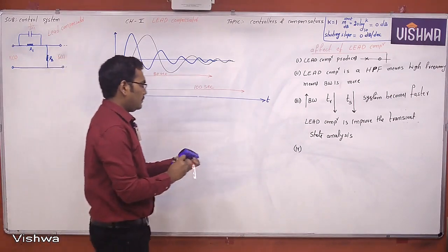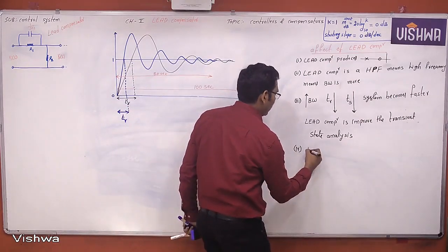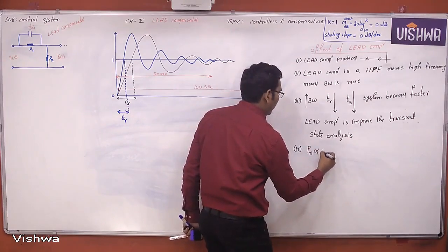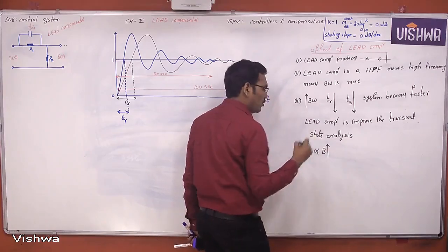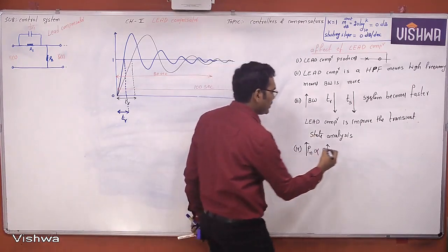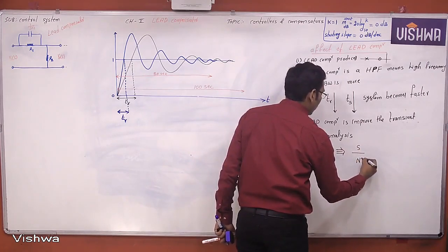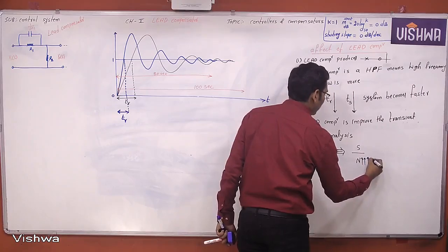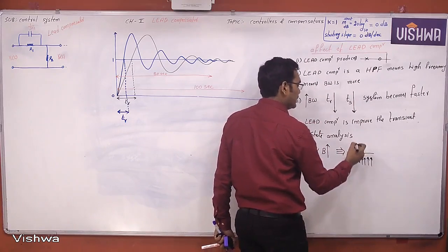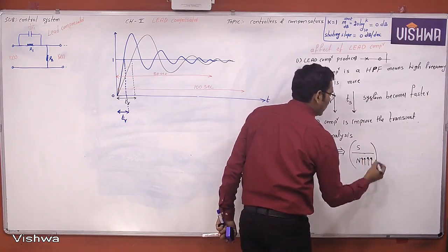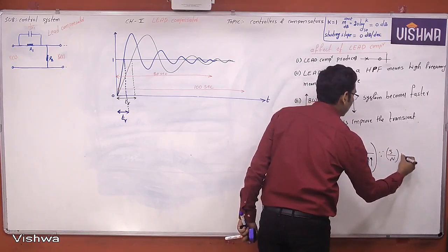Now see here. We know that the noise power is proportional to the bandwidth, but here bandwidth is more, so noise power is more. So what happens when noise power is more? When noise power increases, the denominator increases, therefore the signal to noise ratio is less.